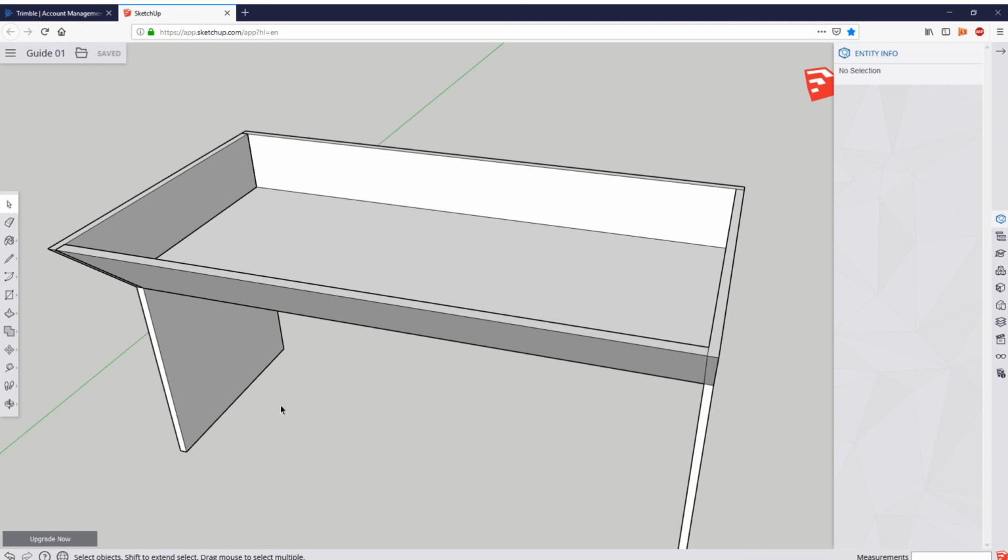So I would use hardwood for the legs here on the side, and I would use hardwood for the back there. For the bottom here, it's debatable. You can probably get away with using normal plywood, MDF, that sort of material, as long as you reinforce it at the bottom with some sort of hardwood beam along the back, for example. It's an option, like a 2x4 along the edge here, to keep it from sagging over time with the weight, and to keep the legs from spreading out to the side under the weight. Could possibly do one at the front as well. That's up to you. Just to reinforce it.